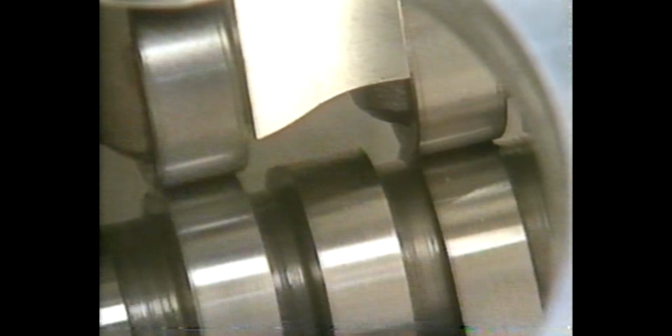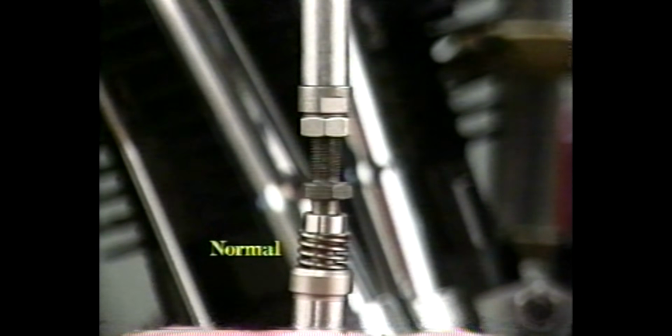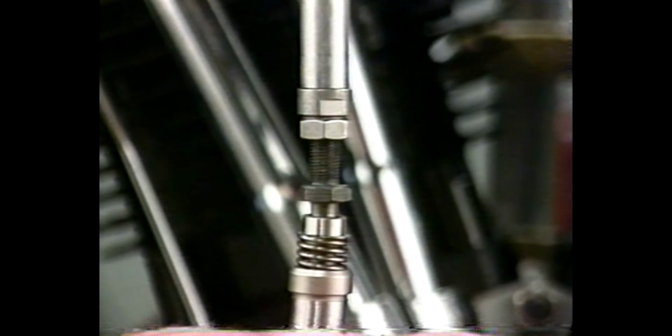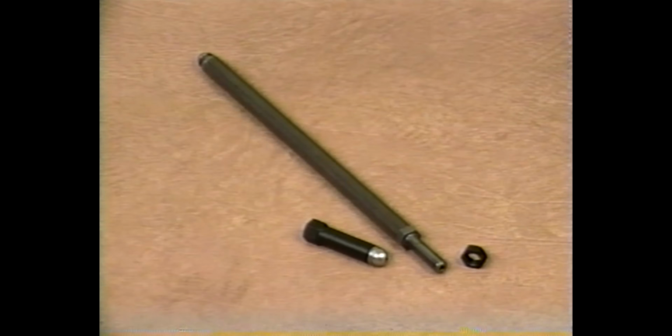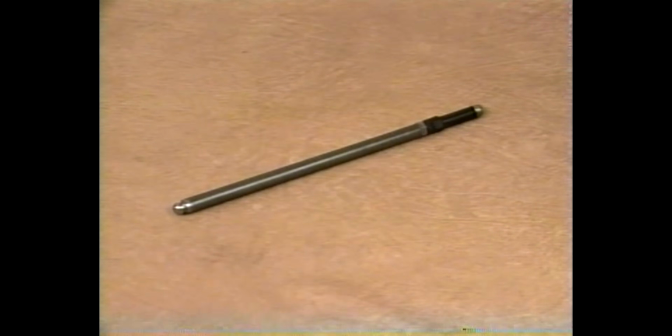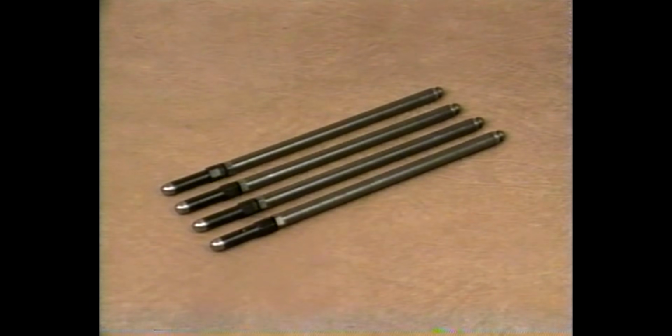The combined effect of the aluminum push rods flexing and the hydraulic lifters pumping up and collapsing further disrupts our sensitive valve timing. When our valve lifts exceed 550 thousandths, we prefer to use adjustable chrome moly steel push rods. The chrome moly steel push rods are slightly heavier than aluminum push rods, but they are also much stronger, more rigid, and less likely to fail in high-performance engines.